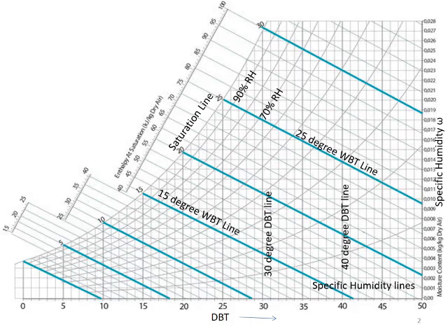So in that case you draw a separate parallel line to the dark blue colored lines. Then what are those light blue colored lines? They are nothing but the constant enthalpy lines. It starts from 15 to 25, the next step 25 to 40, 40 to 100, right? So for each division you have to find out what the graduations are, into how many parts it is divided.